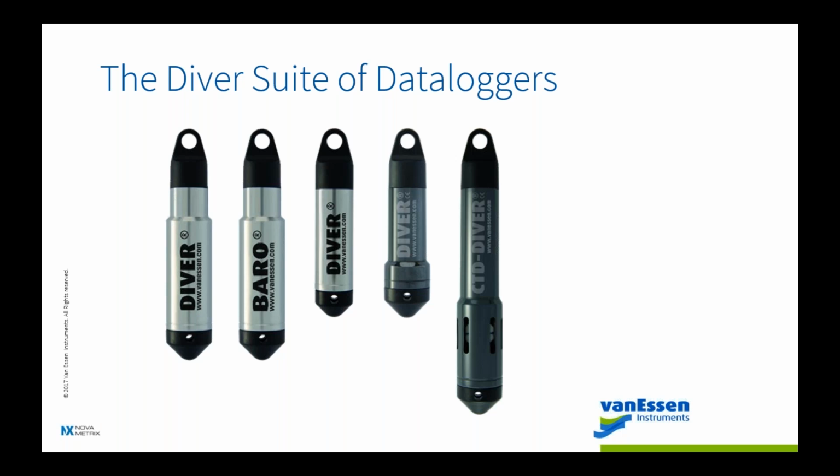The next diver over is the Baro. I always say that no network is complete without the Baro, because I don't know if you can tell from these images, but our units are completely sealed, and there's no influence from atmospheric pressure in terms of these units being vented. They're not. We are absolute only.